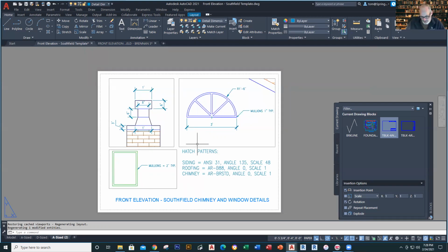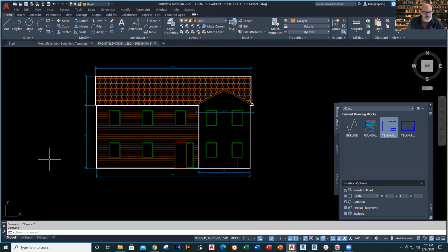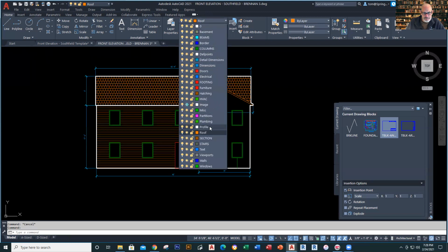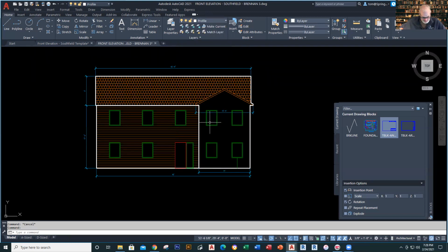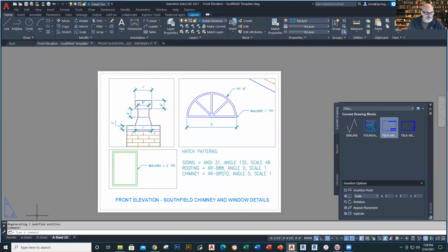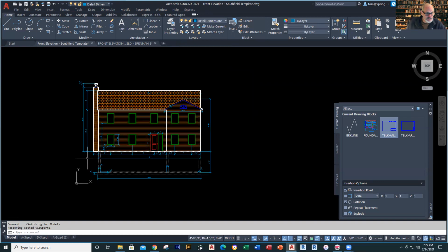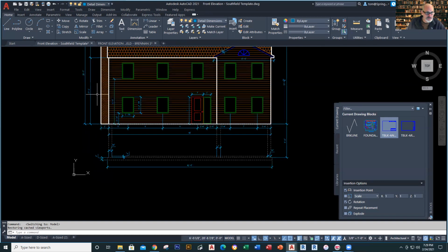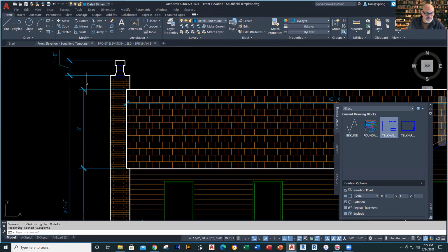I'll just do a little bit more, and then I think I'm going to pretty much bring this to an end right here. The last thing I would do is go over here and use my profile and make my chimney. Now my chimney over here is going to be 2 feet by 26 feet 7. Let me just show you how that is. It's 2 feet wide, and then it goes up 26 feet 7 up to the top there, okay? And it actually goes behind the roof.